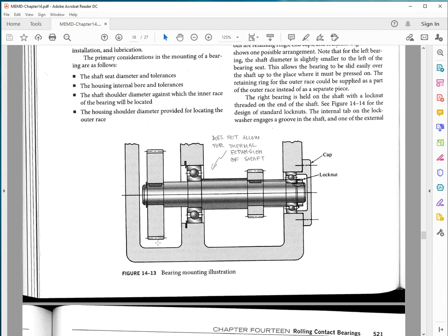There's no knowledge whether there's the possibility of disassembling the left side of the housing, to where indeed you can insert from the left the two gears on their shaft with the bearings readily assembled. So yeah, if I can remove this side, then I could insert the assembly from the left.